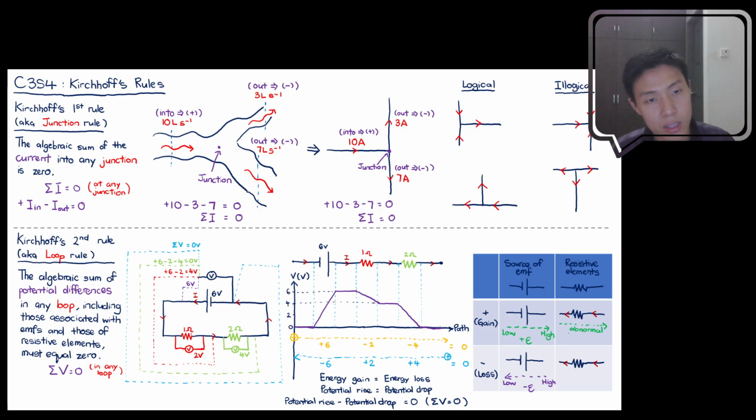Okay, so in this case, abnormally things behave the opposite of what we usually understand. We know that if you pass through a resistor, your charge will lose energy. So if you analyze it in an opposite way, it will gain energy. So this time you put positive IR, because we are talking about resistive elements. If they follow Ohm's law, then you can say V equals IR. So therefore you can write positive IR.